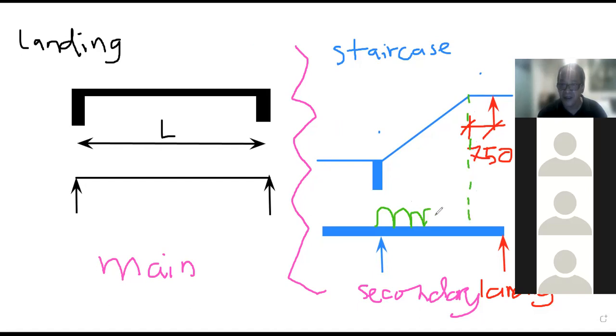Okay, the loading to be considered on the staircase component is at the end of the inclined section sahaja. For the horizontal section, loading di sini dianggap zero. This portion ni yang 750, zero loading. Why? Because semua loading di sini, GK ataupun QK, will appear di sini.